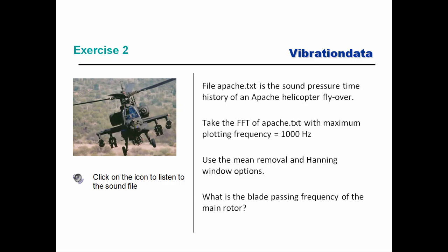So what we have to do is we do different things. We look at the time domain and get an idea qualitatively for what's going on. We might look at histograms sometimes. And then we like to identify what the frequencies are. And there are time domain methods of doing that we've already covered. There are frequency domain methods like Fourier transforms and Fast Fourier transforms. And once we've identified what the frequencies are, then the next task is to determine what those frequencies represent.